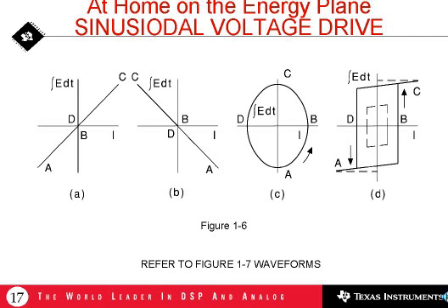What does it look like? If you have a magnetic material which saturates, essentially it becomes like an air core. That characteristic will not go to a horizontal line. That would indicate a permeability of 0, and a permeability of 0 cannot exist. The lowest that permeability can be in the SI system is 4 pi times 10 to the minus 7th. And that might seem like an awfully small number, but it's a number that's responsible.